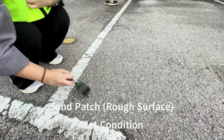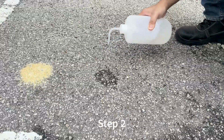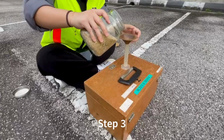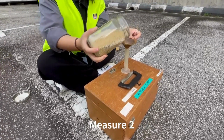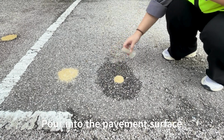Sand patch, rough surface, wet condition. Step 1. Find a dry and clean surface. Step 2. Pour water onto the surface of the road. Step 3. Measure 20 milliliters of sand. Step 4. Pour it onto the pavement surface.